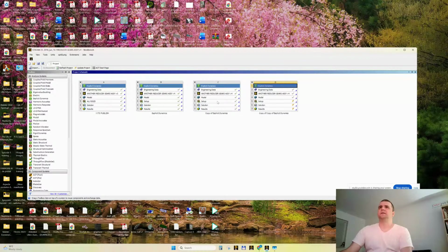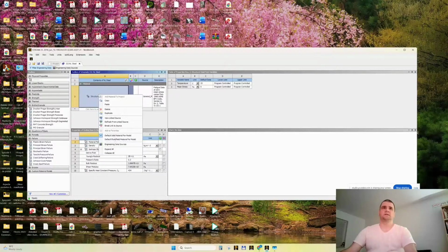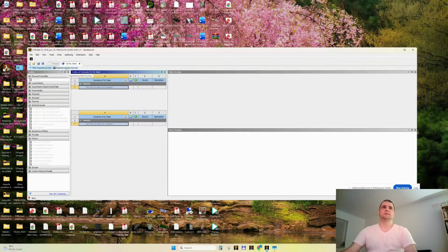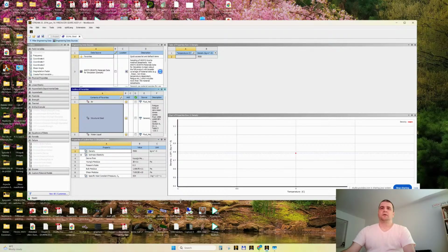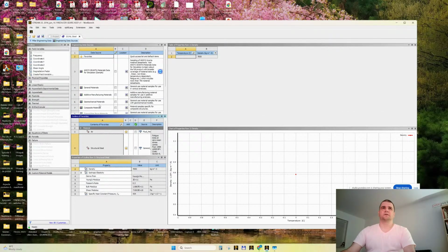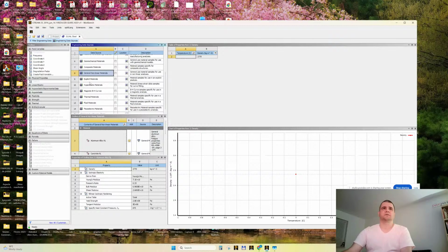So I will be here, flexible plus rigid. Here I will say all, and here we will say NL steel, nonlinear steel. All right. Also flexible and rigid. So as I said, let's delete this and see what changes the nonlinear materials induce in our simulation.